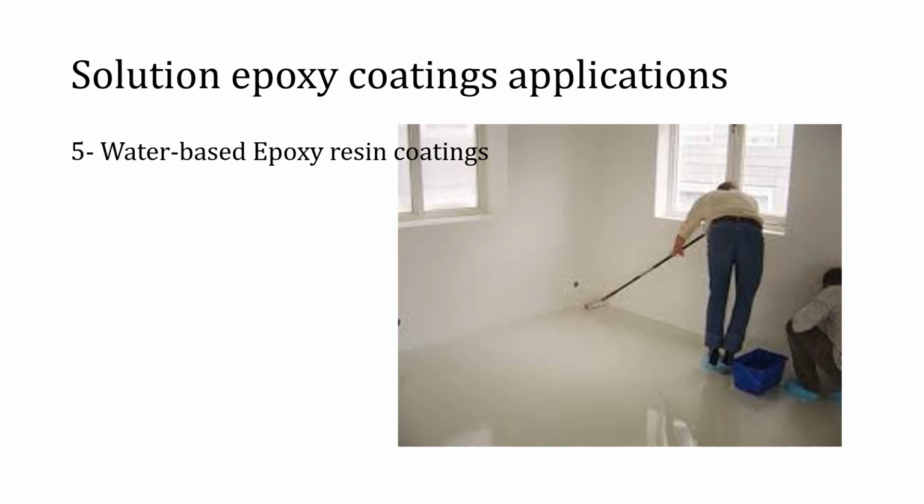Emulsifiers often contain a hydrocarbon tail and a hydrophilic head, perfectly tuned to make stable emulsions of epoxy resins that suit the applications. Generally, to establish a stable epoxy emulsion, the droplet size of the emulsion has to be less than 1 micrometer. Moreover, the aggregation and particle coalescence of the droplets have to be avoided by employing a suitable emulsifying agent. The stability of the emulsion is also affected by temperature variation, as it affects the hydrophilic-lipophilic balance, or HLB balance, of the surfactant.